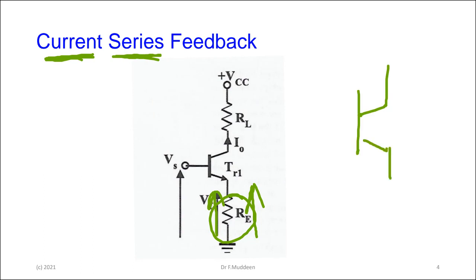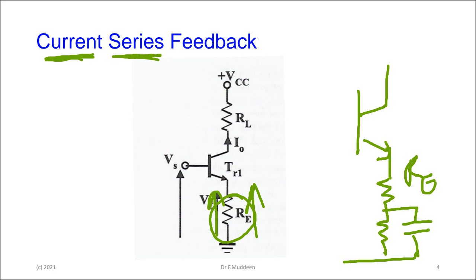Yeah, and you would have met that without knowing it when you did these designs where you have the transistor and you have the emitter resistor, and part of the emitter resistor was bypassed, right? That is when that part is giving you the gain stabilization, but this part here is actually giving you a little bit of current series feedback that does some improvement, as we'll see when we do a little bit more of the lecture later on.